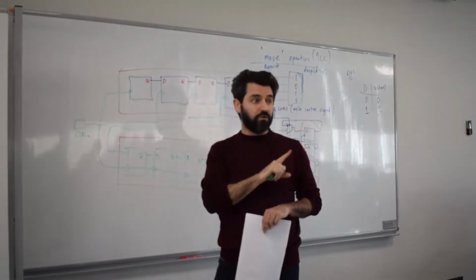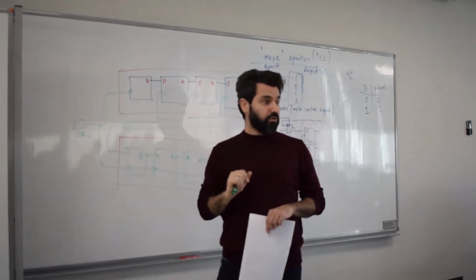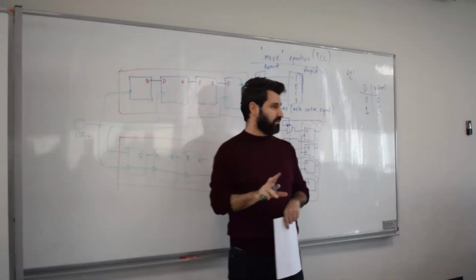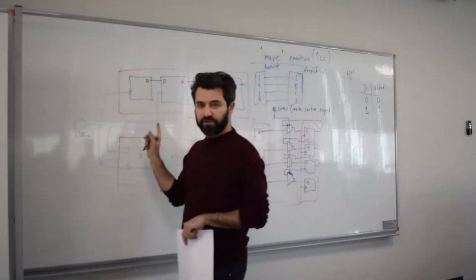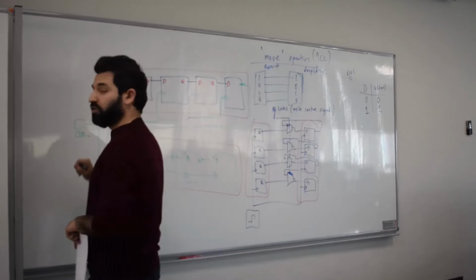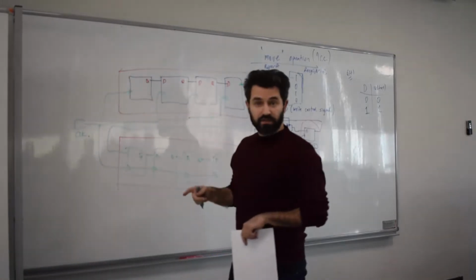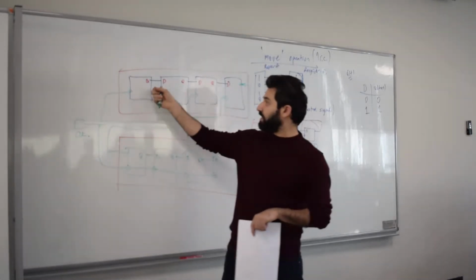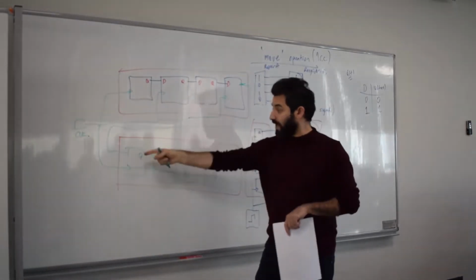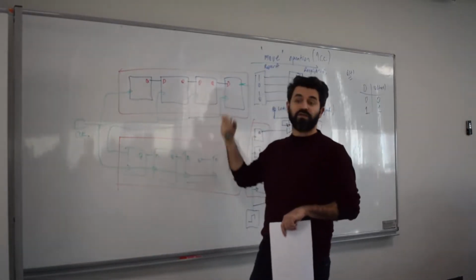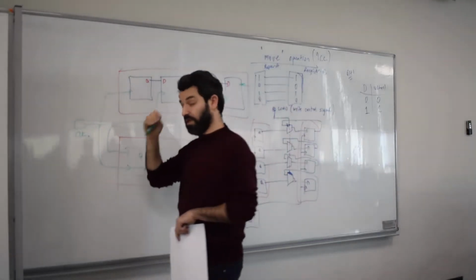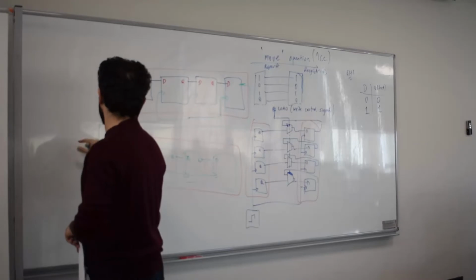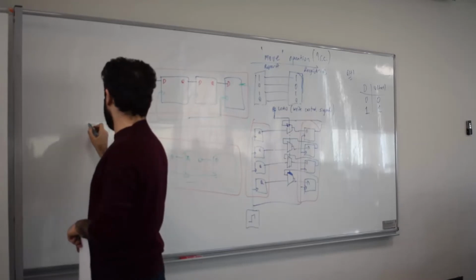a good practice, by the way, because that can cause you to do some asynchronous stuff in your circuit. That's not recommended. Okay, but for this particular case, I'm going to introduce the same delay for everybody, so that is okay. However, if you introduce a gate, for example, for these type of flip-flops and not for these ones, then there's going to be an asynchronicity between them, which could be detrimental. So that's why I'm not recommending it.